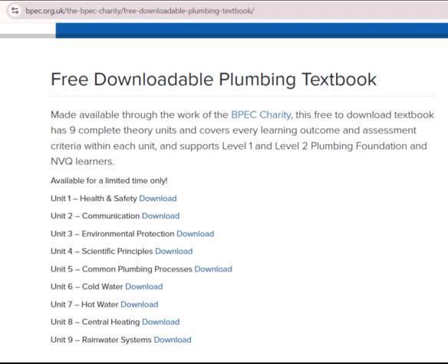A. Pumped heating with gravity hot water, semi-gravity. With this system, the secondary hot water storage cylinder is heated by the heat exchanger in the cylinder. The primary flow and return are heated by the boiler and the water circulated through the coil heat exchanger by gravity circulation. The heating circuits are heated with water that is pump circulated from the boiler. The pump is installed on the flow pipe, as this gives better flow rates through the radiators, because the hotter, less dense water is easier to circulate through the system.